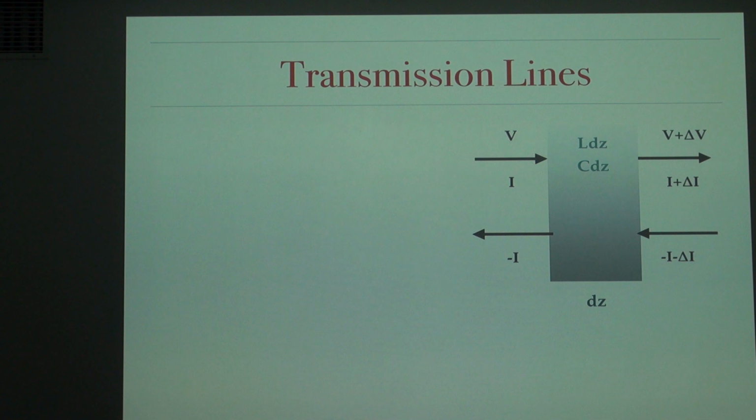And that kind of circuit is easily analyzed mathematically because I can now make a continuum model of it. So I have no coils connected to each other, but I have a certain distance dz, which has impedance per unit length L. And the same piece of the wire, of my coaxial wire or my transmission line, has a capacity C per unit length, dz.